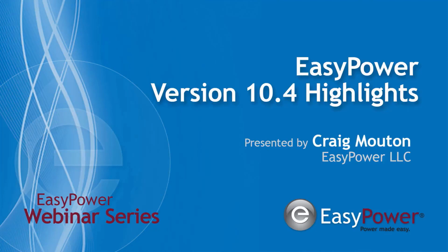EasyPower now supports single-phase modeling on the one line. This includes single-phase taps from three-phase equipment using a line-to-line or line-to-neutral connection, taps from single-phase three-wire equipment using a line-to-line or line-to-neutral connection, for example, a 120/240 volt connection. Short circuit calculations including reports and equipment duty analysis, arc flash calculation including reports and labels, protective device coordination and TCC plots, and device load calculations.